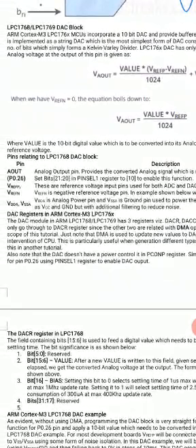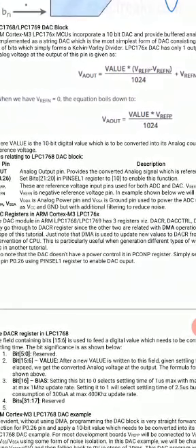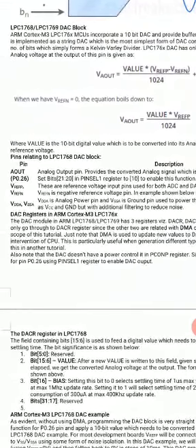Okay, so there is one procedure in ARM Cortex M3 board. There are some registers called pin select. You can see here PINSEL 0, 1, 2, 3, 4. If you have to make this P0.26 bit the DAC output, then in pin select 1 there are 2 bits, 20 and 21. If you put the value 10 in these 2 bits, it will enable this function.